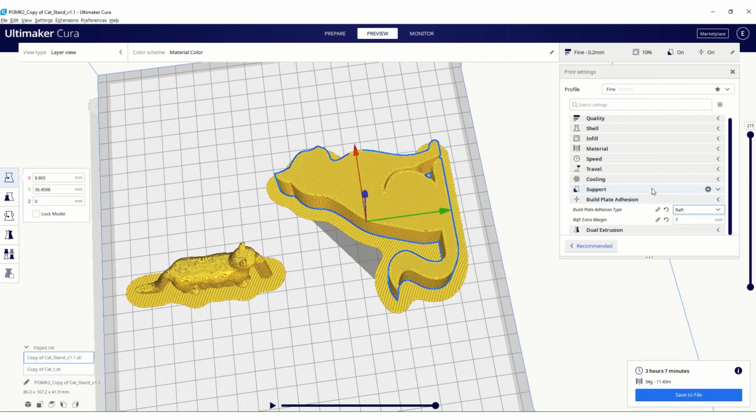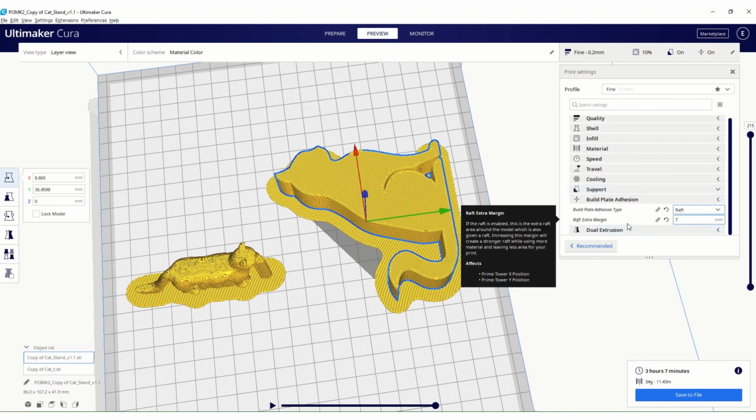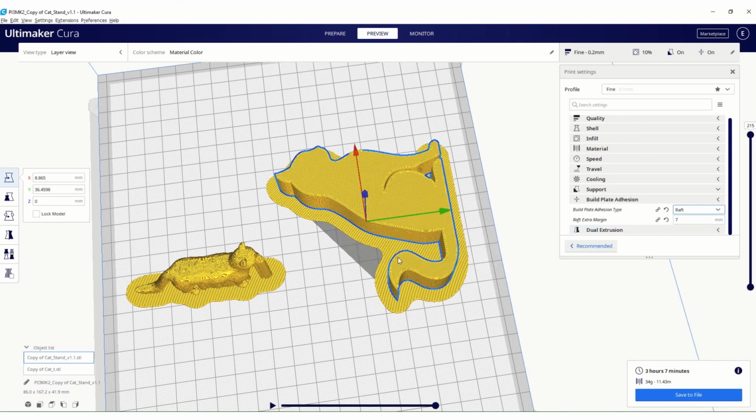So remember that the settings that we have discussed and used are different for each model that comes in. So it's important. Again, I know I've already said this, but let's say if I had this cat, I would have all the perfect settings for it. I might make a profile for flat prints, like nice, easy flat prints, done. Save a profile for that. Call it nice, easy flat prints.